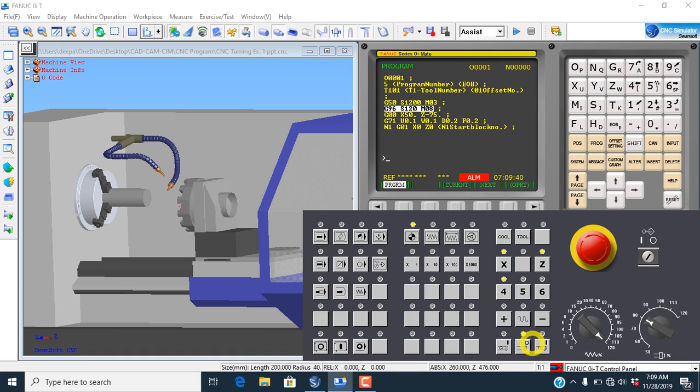These three keys basically control the spindle rotation of the machine. Again, if I want to rotate it, it will rotate. Okay, and it will work when you feed the particular instruction by MDI mode. Presently, that particular mode is activated now. Now, again, I will stop it.